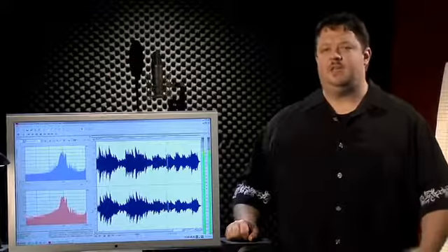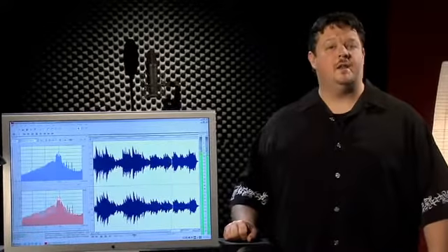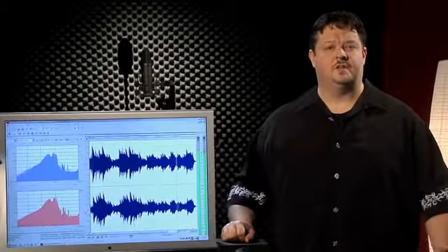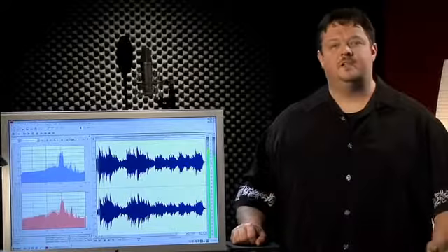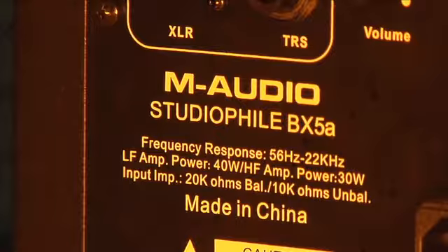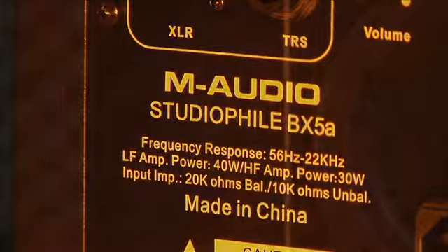The level coming from the main output of your audio interface will probably be either minus 10 dB if you're running an unbalanced line, or plus 4 dB if you're using the balanced output. Since this isn't enough signal to cause much movement of a speaker, and therefore doesn't generate much volume, a separate amplifier is required. Active monitors have specification-matched amplifiers built right into the enclosure.